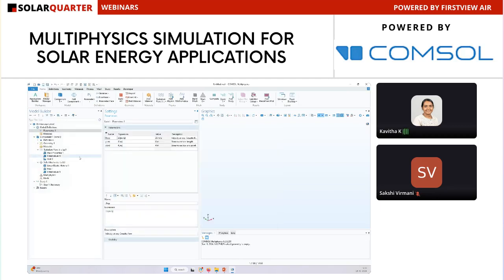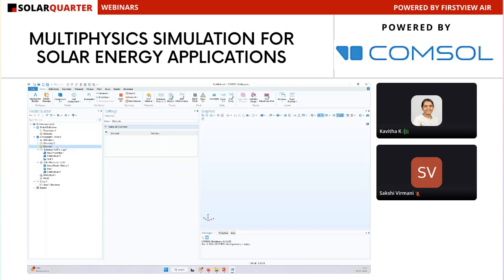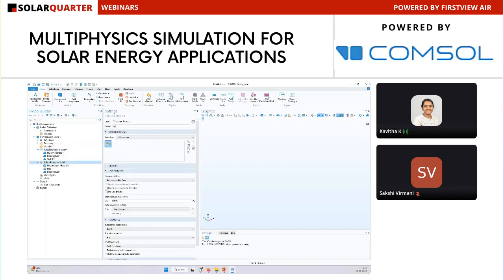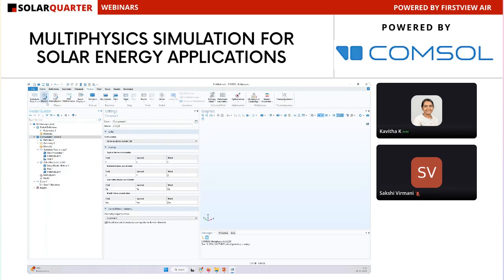So you can load it from file, or you can write down your parameters to model the geometry, or parameters that will set up your physics boundary conditions. Then you create the geometry, then you assign materials, then you set up the physics. Here we have told which physics interface we want to include. Furthermore, you can keep adding in the same window. You can right click and choose add physics, or you can go to the physics tab and add as many physics as you want.